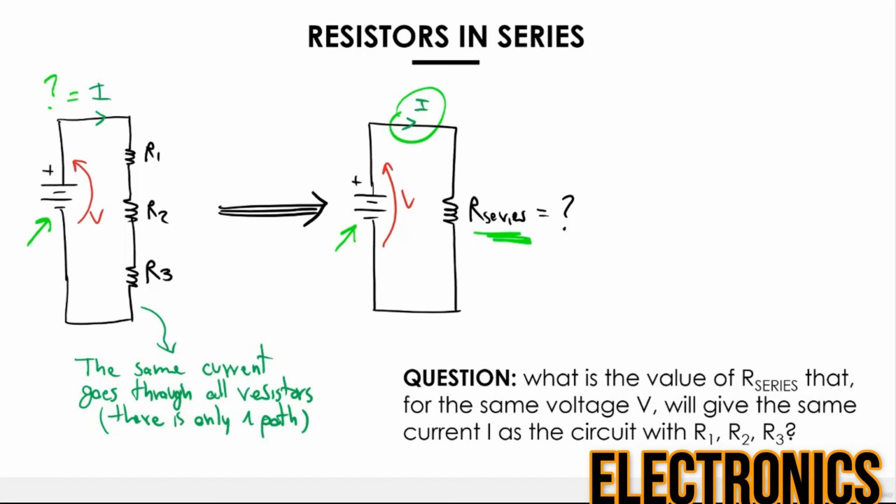In order to do that, the first thing we want to do is to give a name to the voltage across the three resistors. Because the resistors are called R1, R2, R3, we're going to call the voltages V1, V2, V3. The orientation of the arrow of the voltage is random. Of course, I already know the result, so I put the orientation the smart way, but even if you place it upside down, you can still get the right results if you follow the Kirchhoff voltage rule. So anyway, just random orientation from the top, and that's it.